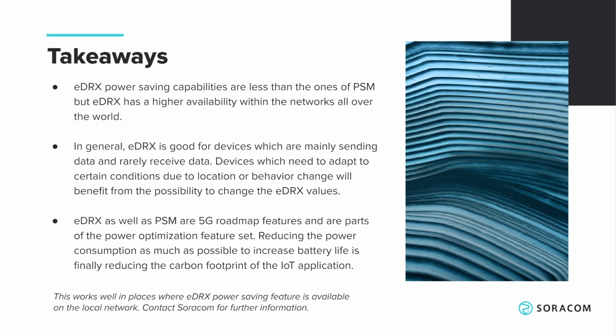eDRX is mainly good for devices which are mainly sending data and rarely receiving them, because we disable the receiver part. And especially devices which need to adapt to certain conditions will benefit from being able to adapt the eDRX setting via this API push.